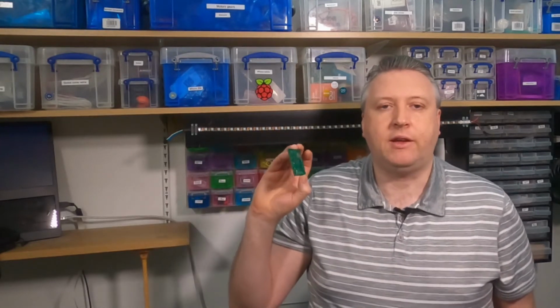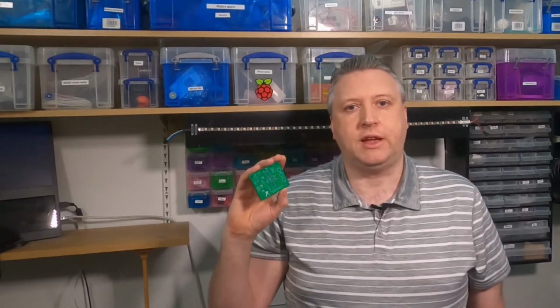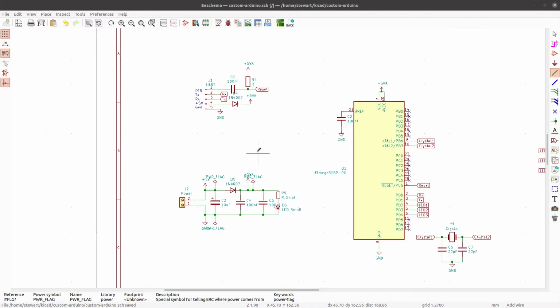This PCB is based around the ATmega 328P microcontroller. This is the same microcontroller used in the Arduino UNO and similar boards. The next stage is to take these components and relate them to a physical component, because although we've said, for instance, this is a capacitor, there can be a huge difference in capacitors, from big chunky electrolytic capacitors to tiny little disc capacitors. And so we need to tell it what kind of capacitor we've got, and that's done through this tool, assign PCB footprints.